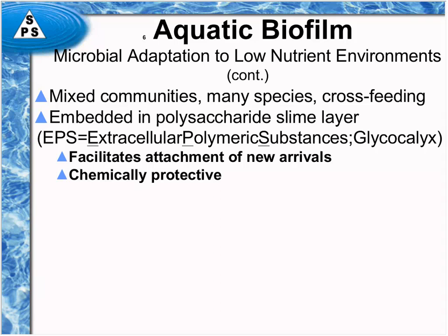The biofilm also, because the slime is mostly water, it's probably only 5% dissolved stuff and 95% water. It winds up being chemically protective just because it provides a thick blanket around the cells. And also the presence of small amounts of organic matter inhibits the action of many disinfectants that tend to react with the organic matter that's in the slime without actually ever penetrating deep into the slime and actually killing the cells.